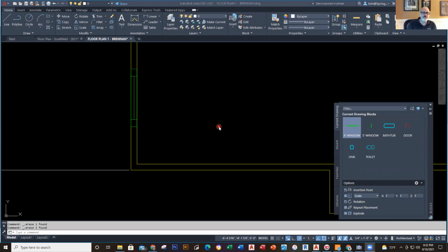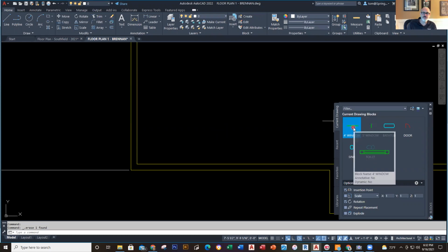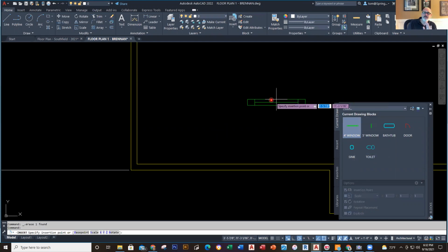So we're actually talking about placing blocks, and we talked about placing this block right here, which we just did, answering that question. Again, just to show how this works, just for the sake of having it on the video: when you want to place a block, we click on the block. When we have it attached to our cursor, we touch it right here and then pull it up. As we do that, we see a dashed line. This is what AutoCAD allows us to do with the extension object snap. So I can tell it how far I want to go up. I'll type in 5 feet, hit enter. And then at that point, I can rotate it around.